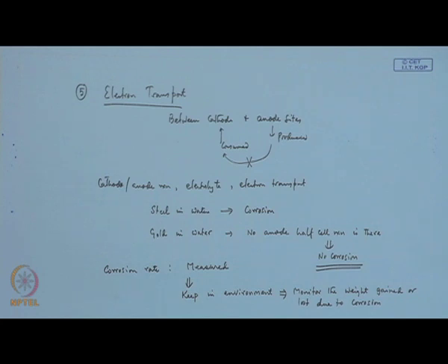So you monitor that. That is the simplest way. You take a clean piece of iron and keep it in the atmosphere, and you measure the weight.